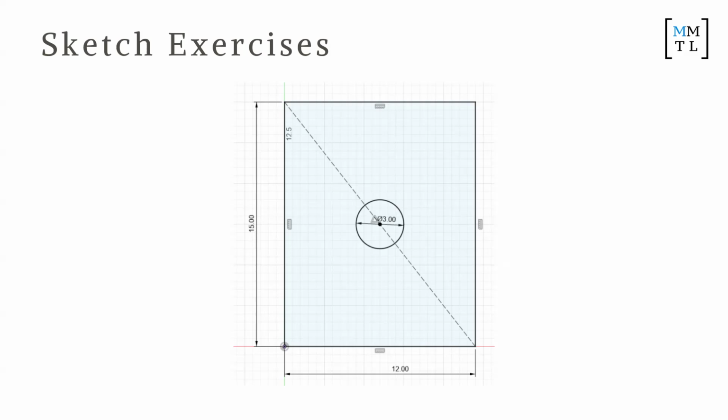Oh wait, no, I didn't, sorry. Because if it's not on the origin, even though you've dimensioned the length and the width, the positioning of it can still change. You notice even if you dimension, the red lines can move, but the fact that we started here means that you have to make a right angle triangle on an axis, not next to an axis. It has to be on an axis, like on the X axis, on any surface.